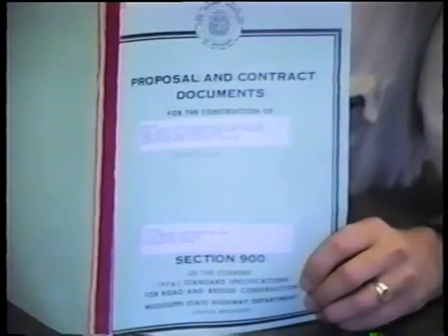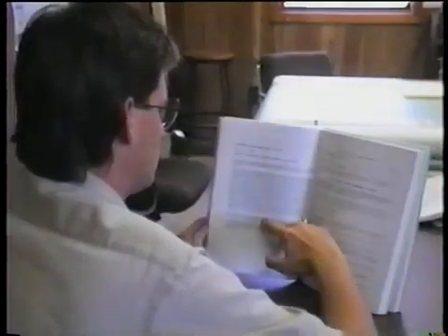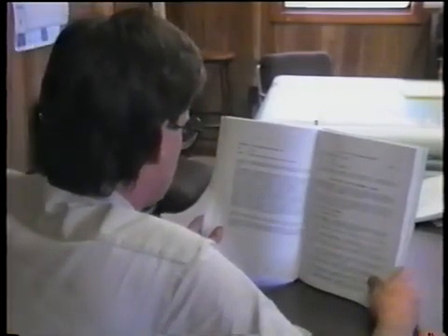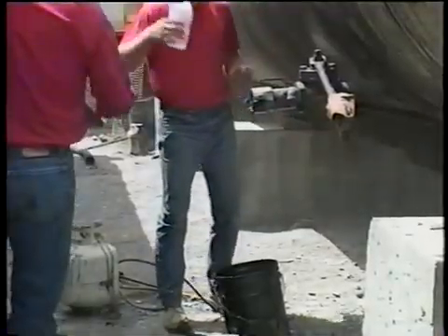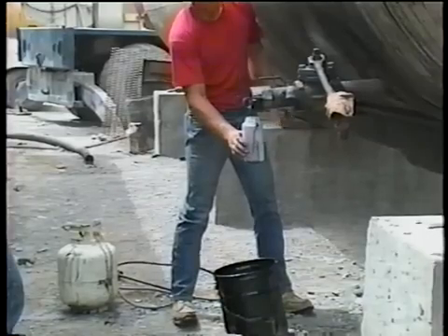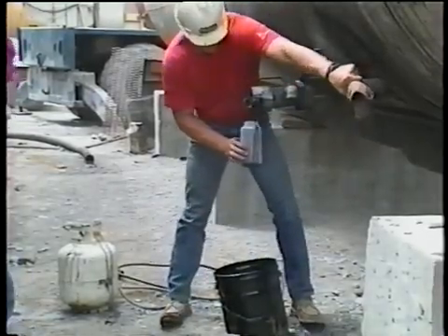But there is a lot to inspect. To begin, check the contract documents to see what type of tack material is to be used. Most agencies require emulsions, but some use asphalt cement or cutback asphalt. As inspector, you may have to sample the tack. If so, be sure to follow your agency's procedures for collecting, documenting, and submitting the samples properly.